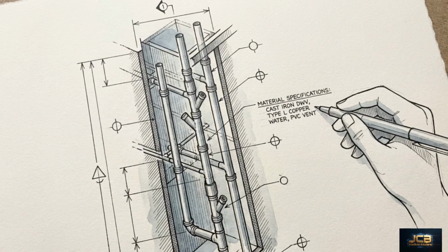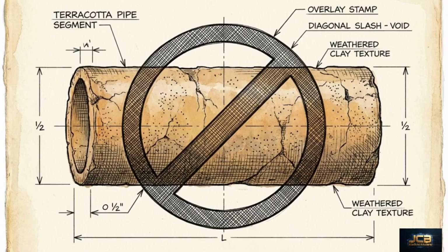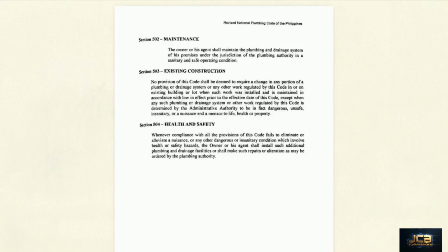With the load calculated, we must select the correct pipe material. Cast iron and PVC are standard choices for vertical stacks, but the code imposes strict environmental prohibitions on certain materials. Reading Section 701.2.1, galvanized iron or steel pipe is forbidden underground and must be kept 152 mm above ground to prevent corrosion.